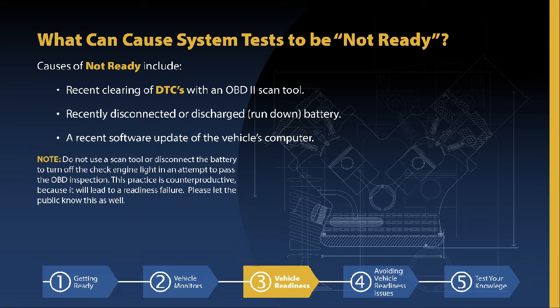Do not use a scan tool or disconnect the battery to turn off the check engine light in an attempt to pass the OBD inspection. This practice is counterproductive because it will lead to readiness failure. Please let the public know this as well.